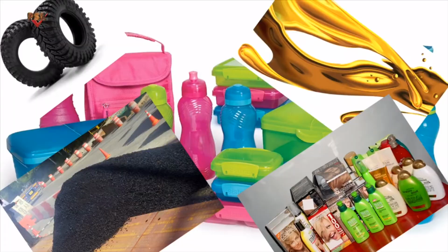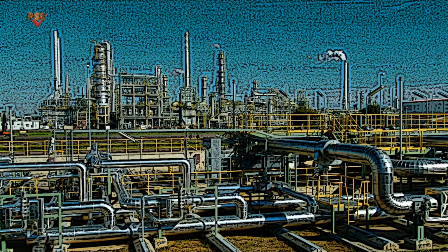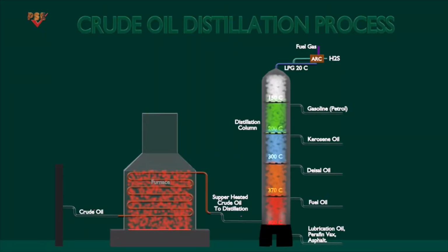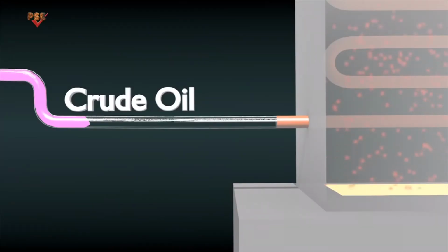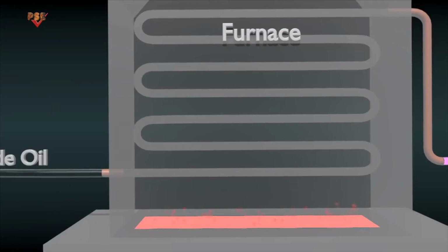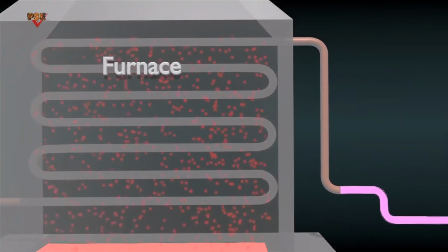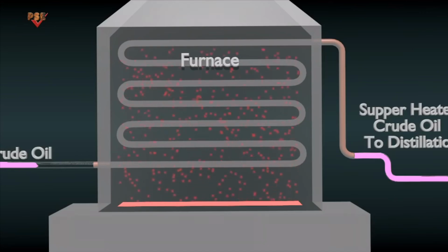The refining process takes place in 3 steps to change the crude oil into finished products. In this process, the first step is to separate the crude oil into its naturally occurring components. This is known as separation and is accomplished by applying heat through a process called distillation. To simplify the process, we consider one tower where the distillation process is taking place. Crude oil is supplied to a furnace before the distillation tower, where it is heated and vaporized and becomes the crude oil mixture.